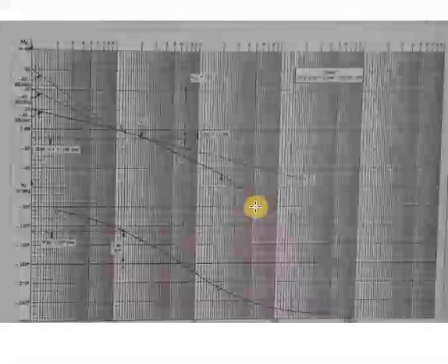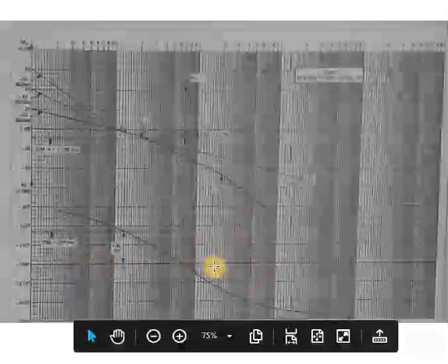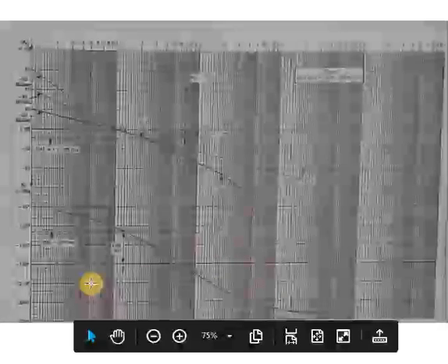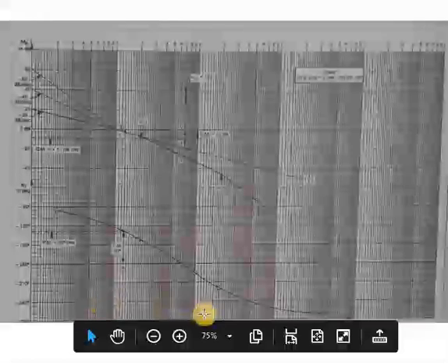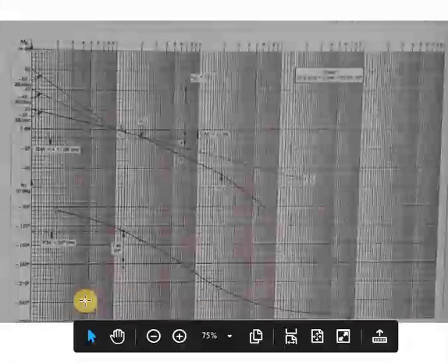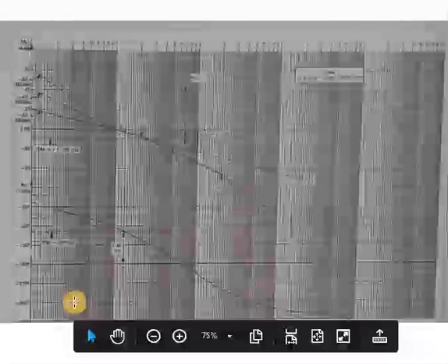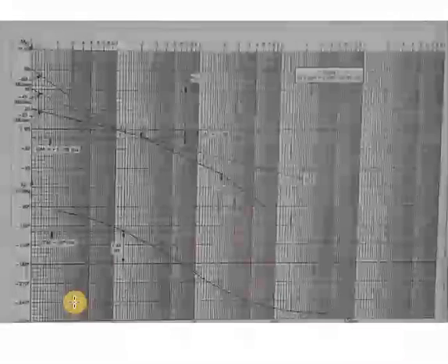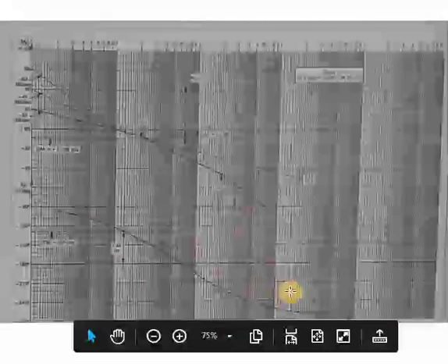After that it will be minus 60. So then you need to plot the phase angle plot. For that, mark minus 180 degree, and along the x-axis you have the omega values. From those values you have already calculated and constructed the phase angle table. So from that table, try to plot this phase angle plot. Join those points with a smooth curve.